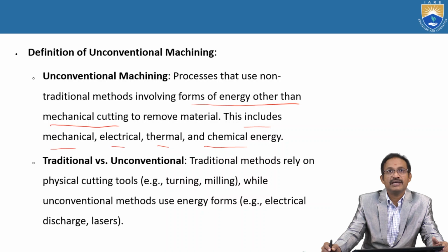So only mechanical cutting forces are related to the conventional machining process. Usually in general lathe machine operation or milling machine operation, in order to remove the material, directly we use single point or multi-point cutting tools to cut or machine the workpieces. So there will be direct physical contact.